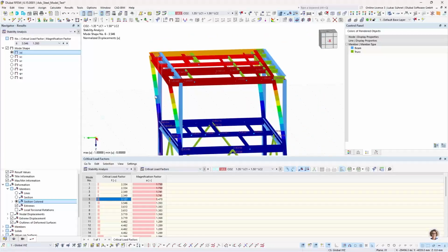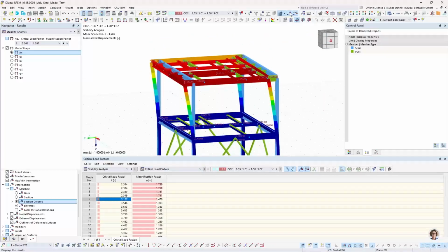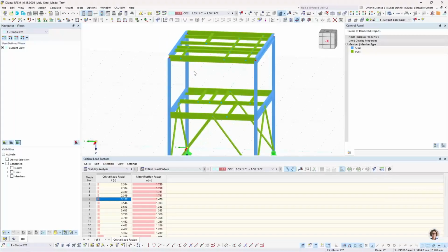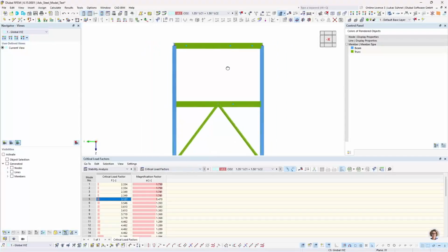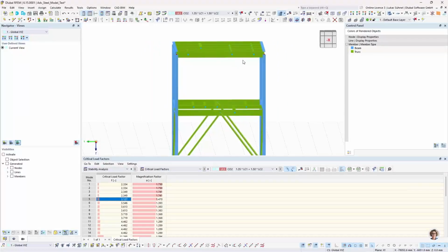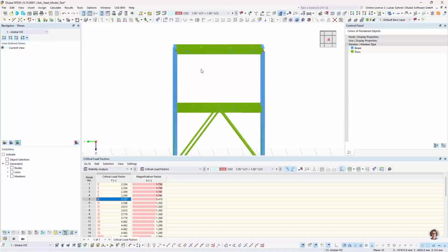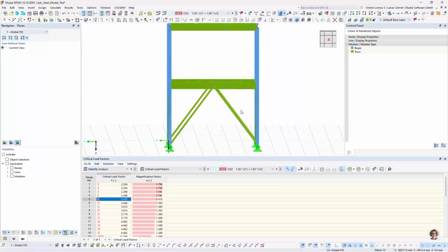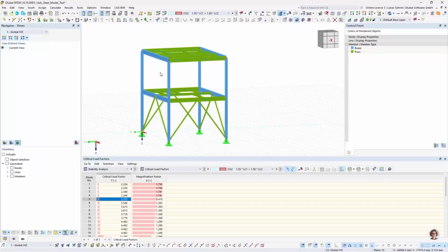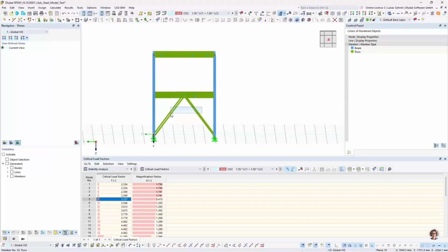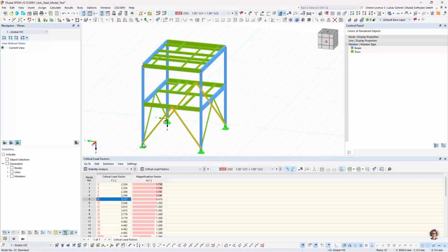And I think it's kind of logical, because in the upper floor we have, as I said, a rigid frame in this direction, but in this direction everything is connected via hinges. So no bending moments transfer. So it's really not very stable. For this floor it's okay because of the diagonals. Here we do not have them. So to optimize my structure regarding stability, I would simply decide we definitely need also these diagonals from the bottom floor and the upper floor.